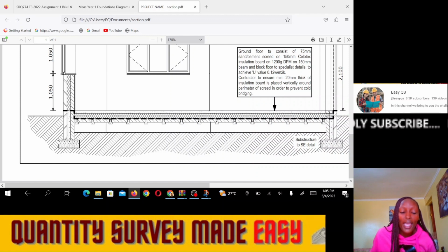So between the end of the trench and the wall, this space that is left here, also called the working space, is also called the foundation spread. So whenever we are measuring for site clearance, we will not only measure the external dimensions of the wall that I'm showing using my arrow, but we'll also add the foundation spread on the outside, because we need to clear all that area and also excavate topsoil for all that area until the edge of the foundation. The edge of the foundation is where I'm showing using my arrow here.